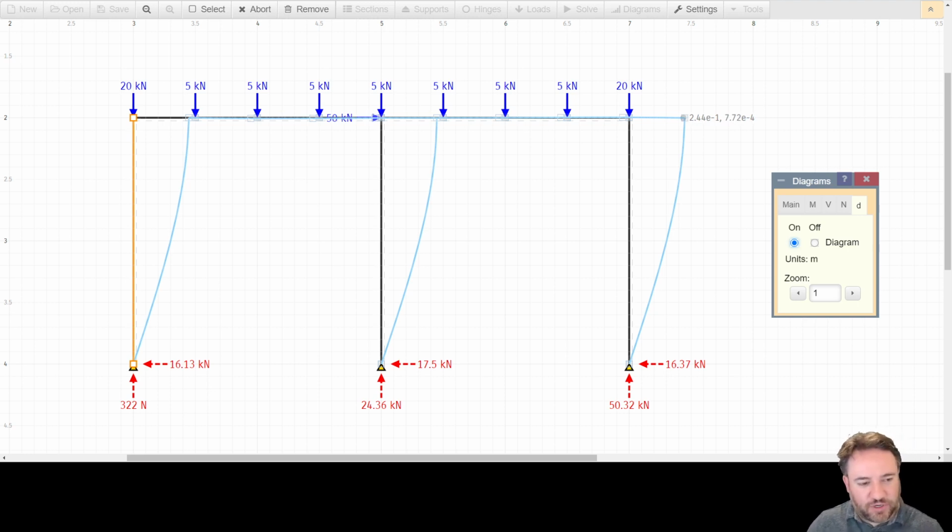So that would not fit an NBCC deflection limit. I would have to beef up my columns if these were my loads, if I wanted to meet the deflection limit, which was an optional part of our assignment. That's basically it. I'm able to get my moments and my shears and show my deflections. Since the beam is much stiffer than the columns, we don't get much bending in the beam. There is some bending, certainly, but relative to the columns it's not very much. So probably what I want to do is beef up my columns.